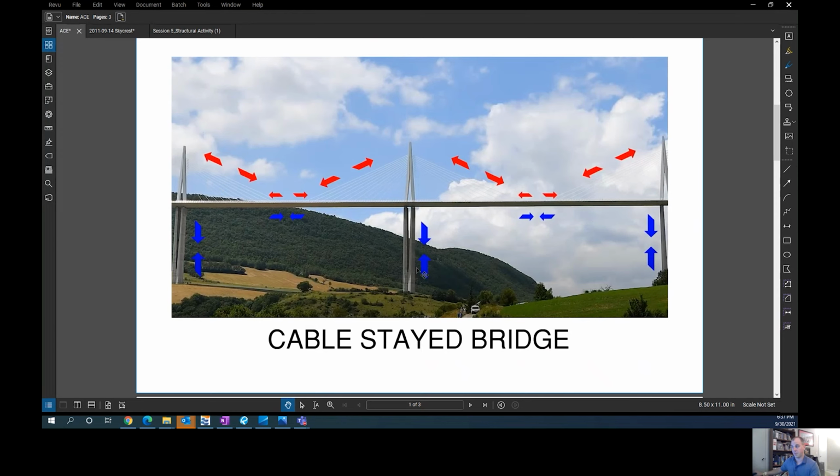In the video, Nehemiah hit on a very important and very helpful element to cable-stayed bridges, and that is that for construction, the cable-stayed bridge can be built off a single pier. If you build in one direction at the same time as the other direction, and at each interval run a new cable back to the pier and hit the corresponding point on the other side, then you can build the bridge in both directions simultaneously at the same rate. This can be done at each pier to the point where they all meet in the middle.